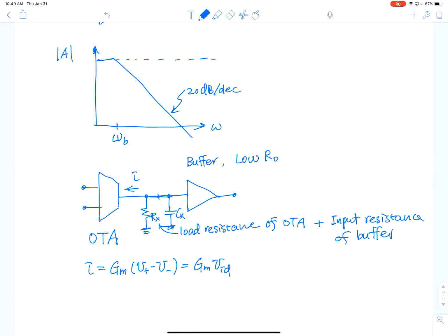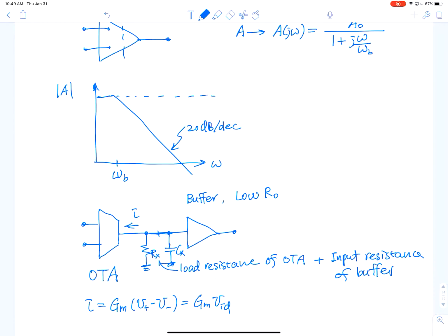These are the transistor capacitances, and the wire linking these two stages together. They all have capacitances. So you end up having created an RC low-pass filter here, and this RC low-pass filter gives you this low-pass response. Does that answer your question? Okay. Any other questions?